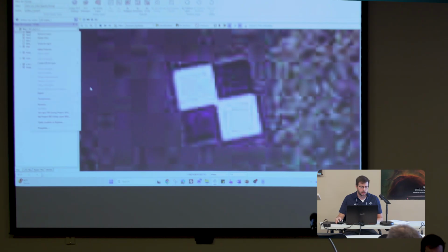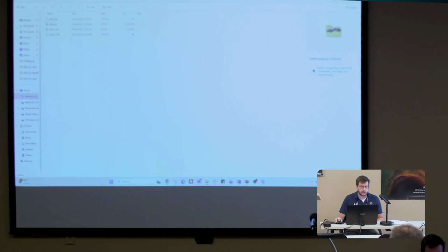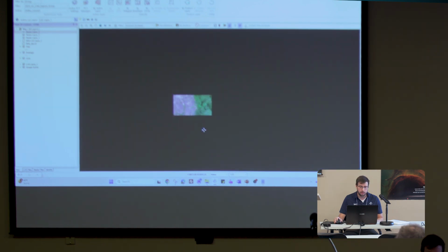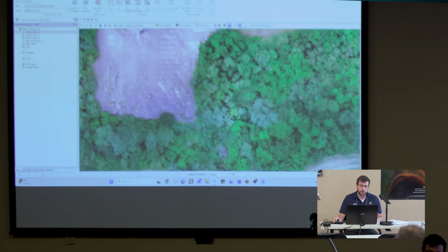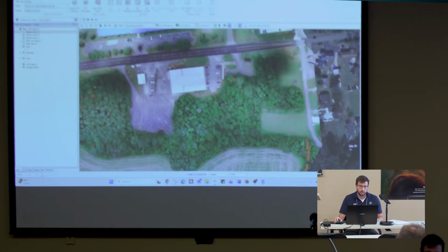And let's right click on that raster layer 3, open location explorer. Let's see. Yeah, I've basically halved it again, so it's less than a quarter size of the initial data that we started with. That 400 megabyte file, I've reduced it to 70 megabytes and really kept a lot of the fidelity there. So I think for most users and most applications, this is going to be the go-to setting and workflow for reducing the quality of the ortho for import into your different CAD packages.